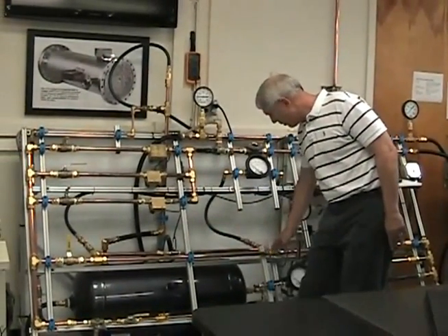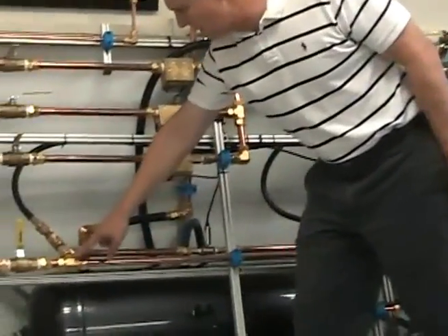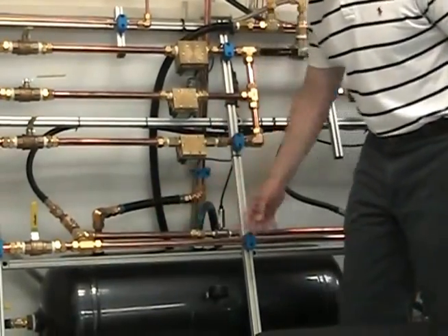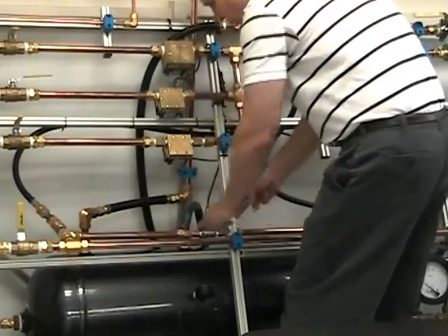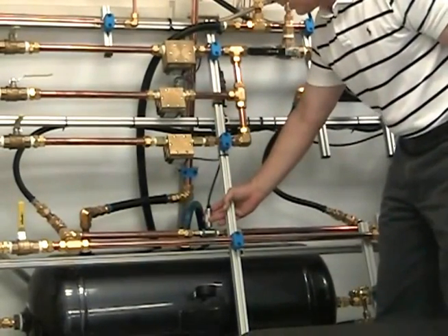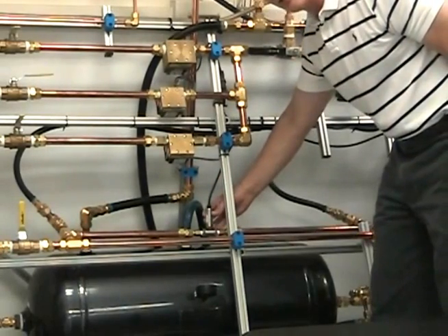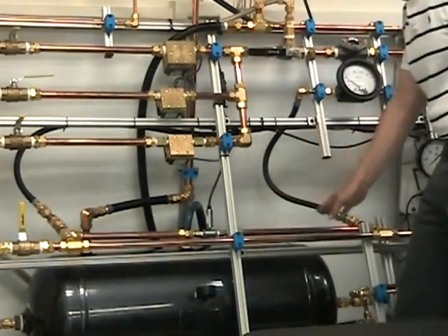So we have a pressure tap right here on this large pipe, and we have another one over here. The flow is going in this direction, so there's going to be some pressure loss in the pipe. In parallel with the pipe, we have a pressure transducer. This is a differential pressure transducer, and it sends out a voltage to LabVIEW, and we can use that to measure the pressure drop. We also have hooked up with this an analog gauge.